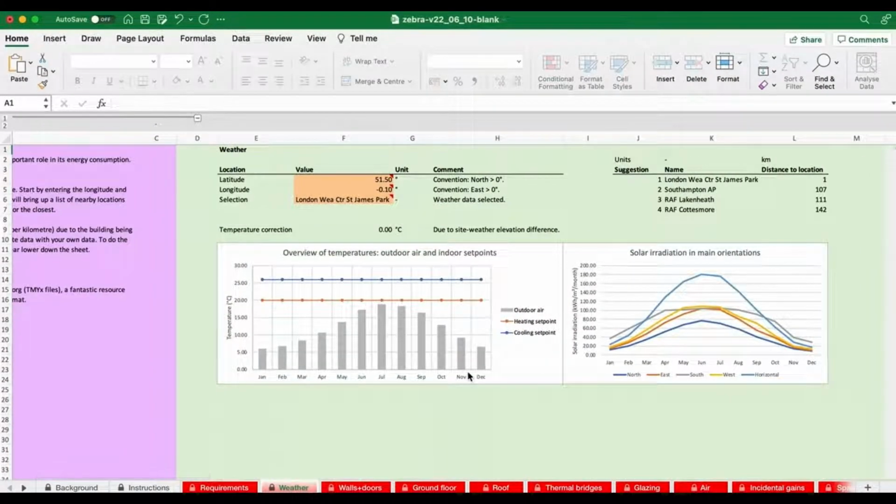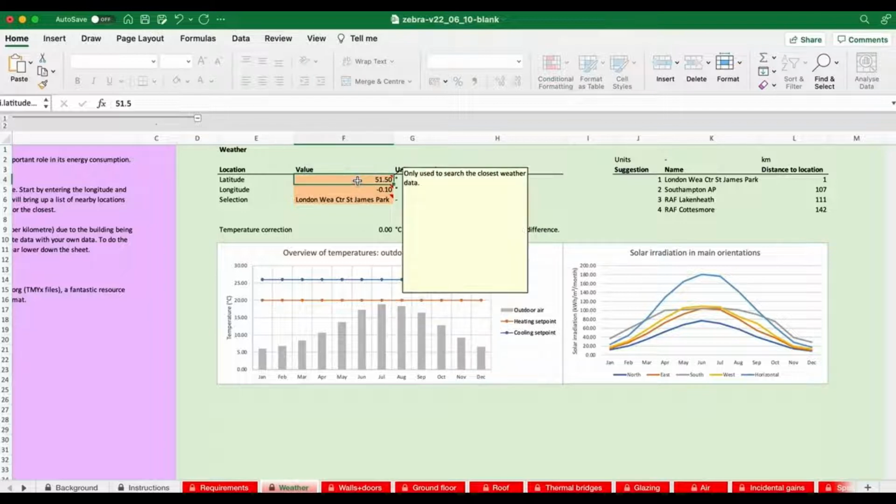Here we see that we can choose a location for our building. Now, looking up the building's lat and long, and this is in table 1, so you could just copy it from there if you're actually just going to copy this building. It's 13.1, so not far north of the equator, and 80.3.